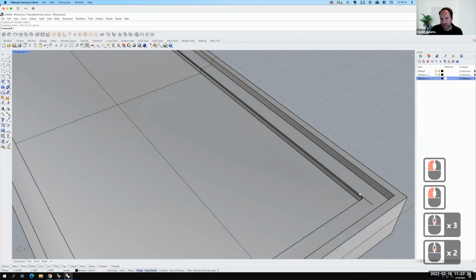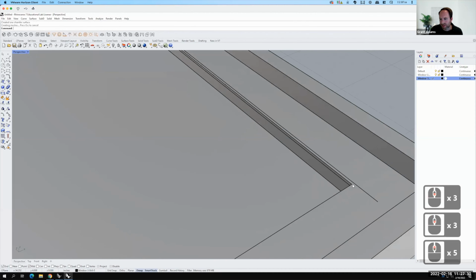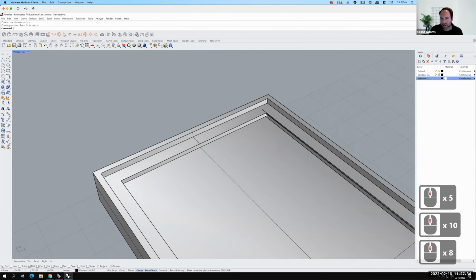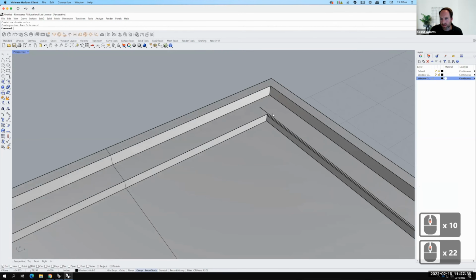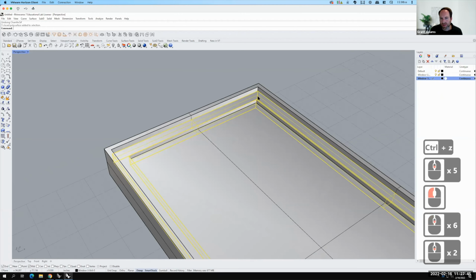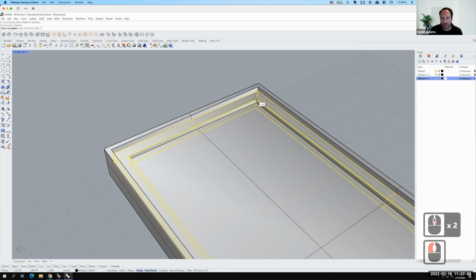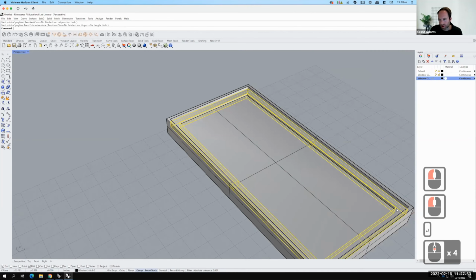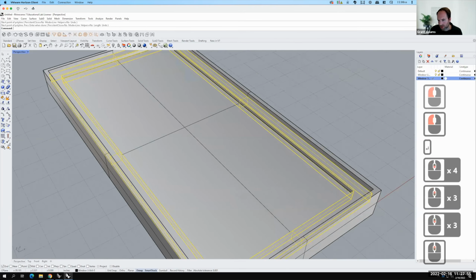Now we've got some issues, and we had these same kinds of issues occur back when we did our bridge. See how that chamfer went beyond my shape? It's a perfect opportunity. Let me press Control Z to undo, to actually split this surface first into separate pieces. So I could draw a line at the corner there. I could draw another line down here at the corner.